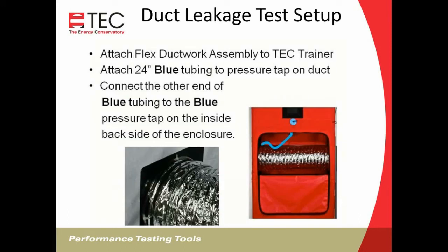Next, if you're doing a duct test, you'll attach the flex duct inside the red nylon panel. Open the zippered opening, attach the ductwork in there.